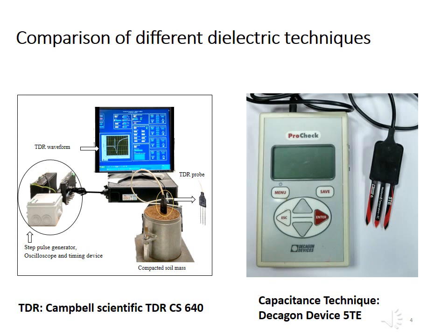The soil was mixed with deionized water and left for maturation for 24 hours, which ensures uniform moisture level of the entire soil mass. Later, it was compacted to different compaction states in a standard Proctor mold as per the ASTM procedure. Simultaneously, 3 specimens of matured soils were used for determining gravimetric moisture content by employing the oven drying method. The volumetric moisture content, electrical conductivity, and dielectric constant of the compacted soil mass were determined by employing these 2 techniques in a sequential manner.